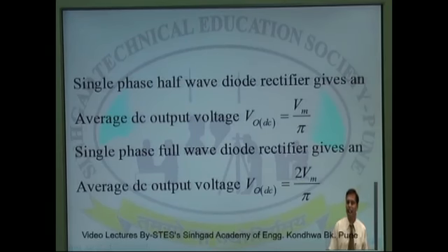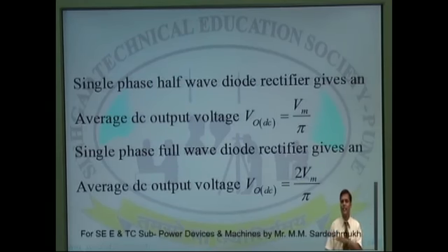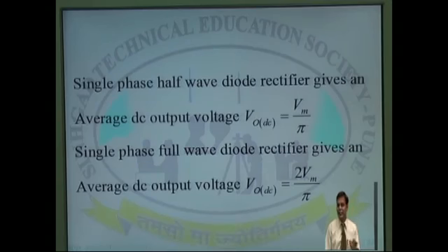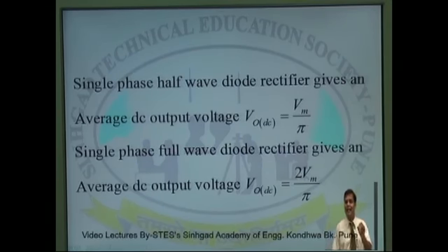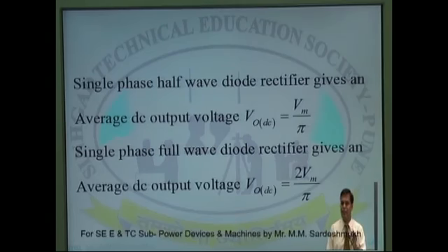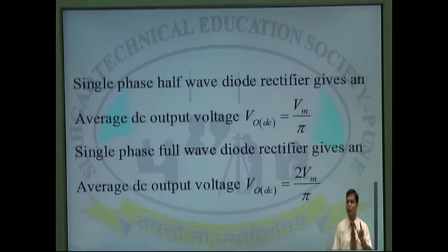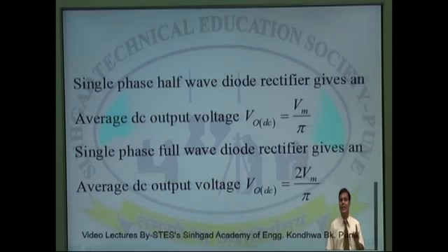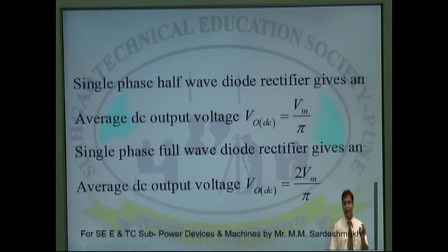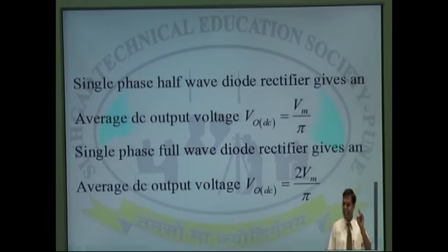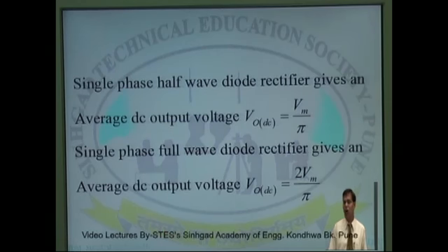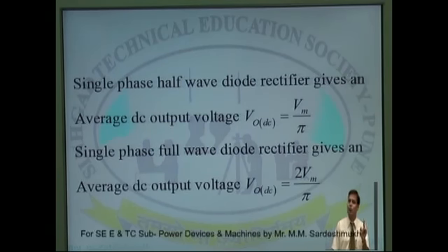This is the case of the uncontrolled rectifier. Totally opposite to it, in the case of a controlled rectifier, I can control the angle alpha, which is the firing angle of the thyristor. As you see in the structure of a silicon controlled rectifier, it is a PNPN structure. Even though forward bias is applied across it, the device is not going to turn on; it will be in the forward blocking state.